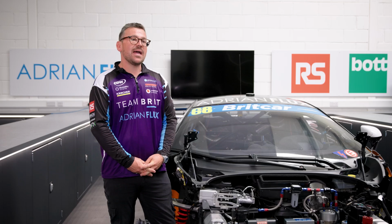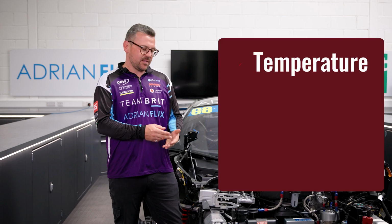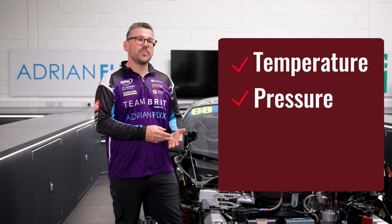Most of the sensors that we add in to the vehicle in a motorsport concept can really be broken down into 4 key areas: temperature, pressure, position and frequency. With a range of those sensors across the vehicle, that can tell us almost everything we need to know about the performance of the car.